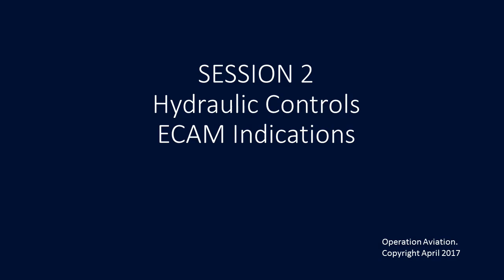Reservoir contents, this is the quantity of the reservoir. It's indicated here by the vertical line with a point on it, and that point indicates the fluid level. The indication is considered normal when that point is within the adjacent green box. The indications become amber, accompanied by an EWD caution message, when the fluid level goes below a certain preset limit.